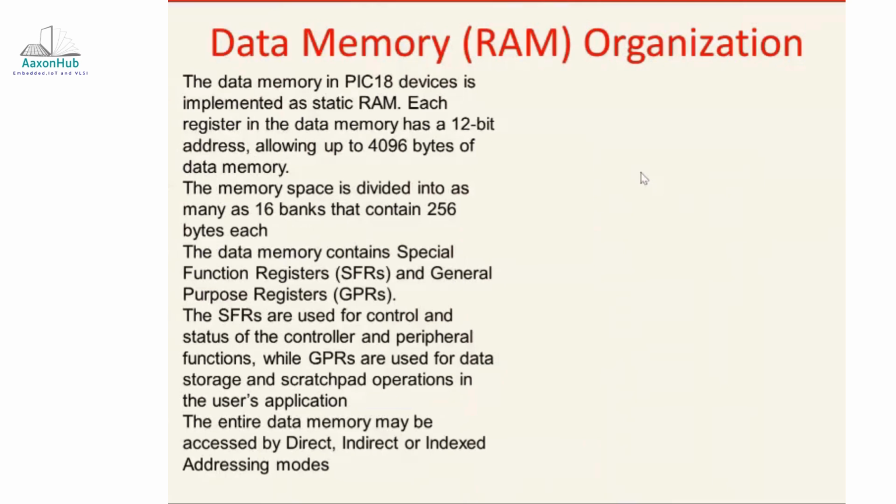Let's move ahead with the data memory. As the name itself tells you, data memory is the memory used to store data. This data memory is accessible with 12-bit addresses. As per the 12 bits, it allows up to 4096 locations, so 4096 bytes will be there for the data memory. This memory space is divided into banks.